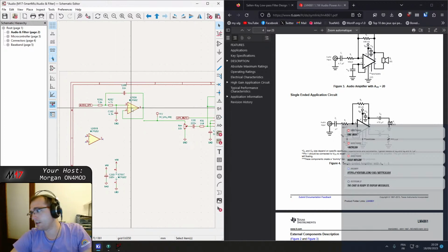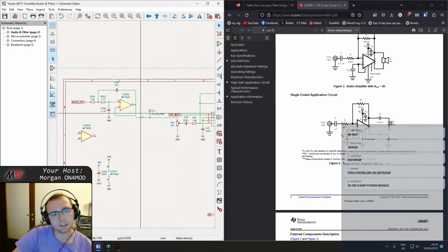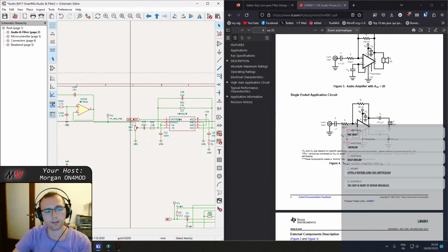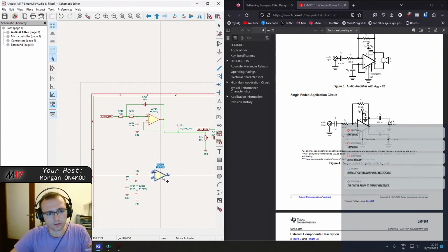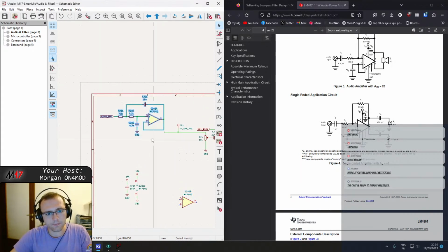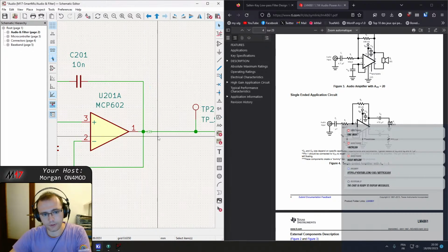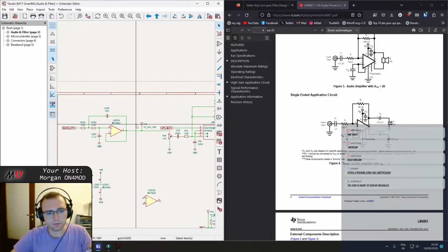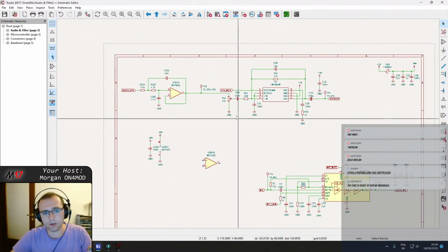This is gonna have a much lower output impedance, which makes it so that the voltages that arrive on the input of the power amplifier are gonna be from 0 to maximum 3.3, and less than that because of the impedance of the filtering. So this should sort things out already. So we can do this, remove this wire and join those two. So this is gonna be our new audio output, I think.